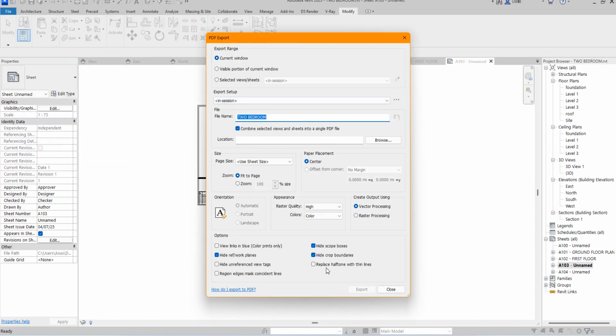So how will you do it? This one is being selected. You see the sheet being selected. You change some of what we want to change here, like the name of the bedroom. What are those things you need to do with it? So you select the sheet and you print them in that area. You select the section in which you want to export. So if you don't have a section, you need to create one. How do you create a section? You just select section and view from here, and you say edit.